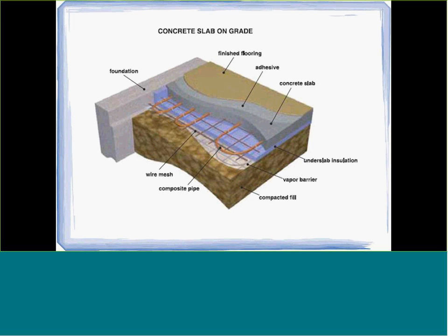use concrete on slab. One thing that you have to remember is that if they're going to saw cut the floor, make sure that your tubing is at the bottom of the slab, and make sure the guys that are doing the saw cuts know that there's tubing under there. PEX tubing floats, so you want to make sure you secure it to the floor properly.